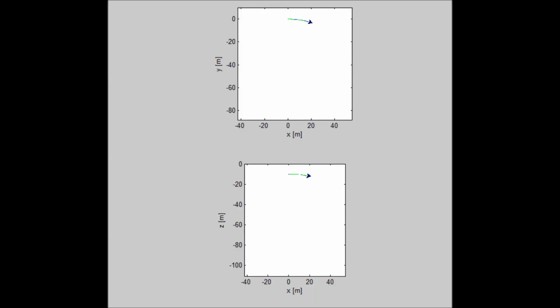The kinematic model was tested using a set of inputs for the velocity and joint angles to demonstrate a helical path. The plot shown on the top represents a bird's eye view, and the plot on the bottom is a side view to show the depth of the TBM as it spirals downwards. The position plot shows the position of the coordinate system based around the rear shield. The kinematic model was derived from the coordinate transformation using the ZYX Euler angles for yaw, pitch, and roll in relation to the fixed reference frame.